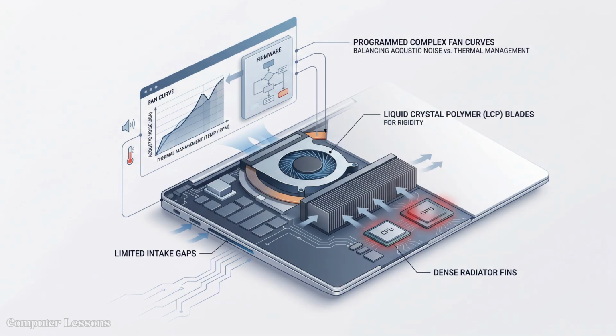Airflow engineering in a slim chassis depends on high static pressure fans designed with liquid crystal polymer blades for rigidity. These fans must push air through dense radiator fins despite limited intake gaps. Complex fan curves are programmed into the firmware to balance acoustic noise against thermal management.